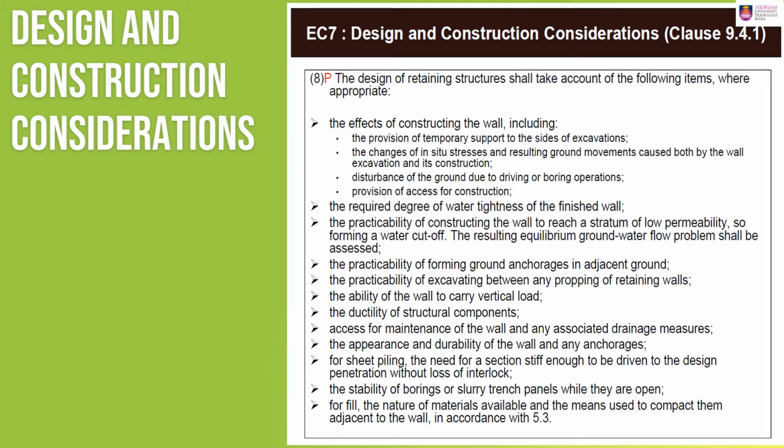For design and construction considerations, the principal design of retaining structures shall take account of the following items where appropriate. First is the effect of the structure of the wall, including the provision of temporary support to the sides of excavations, the changes of in situ stresses and resulting ground improvement caused both by the wall excavation and its construction, disturbance of the ground due to driving or boring operations, provision of access for construction,